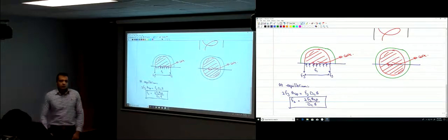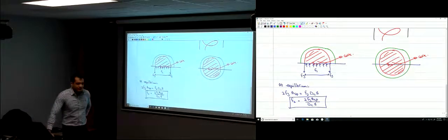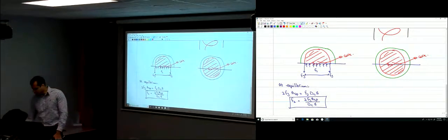Now, last time we said to express how much stirrups you have, for any steel we use rho, the steel percentage. For the longitudinal steel bars we use rho as the percentage or the ratio between the areas. Now for spirals, rho is the volumetric ratio.